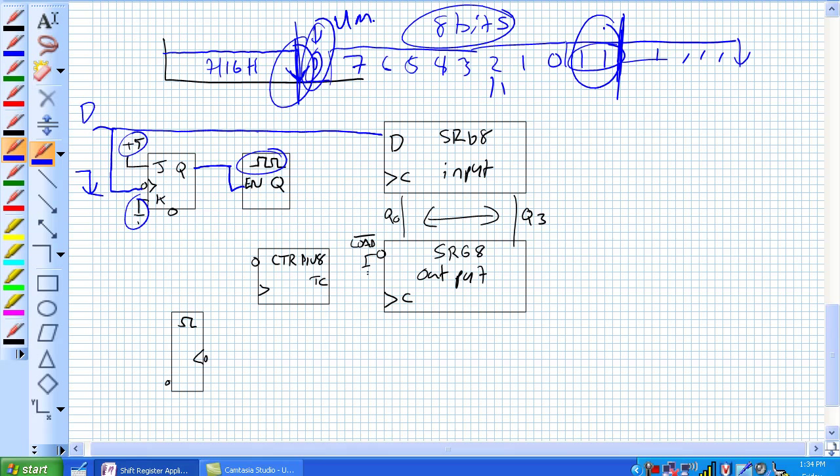of, what is that symbol right there for our ANSI IEEE symbols? Well, 2 pulses there, that's a clock, basically an astable multivibrator. What it's going to do is just basically enable this clock, which goes to our data input register. So this thing starts clocking along at the exact same frequency as this guy right there. Also, that clock signal is sent to our counter, and it happens to be modulus 8 because we're expecting 8 bits.